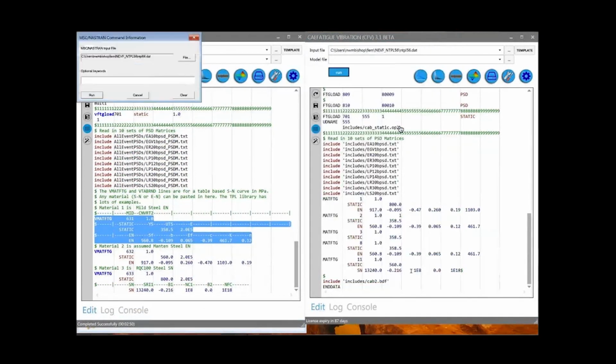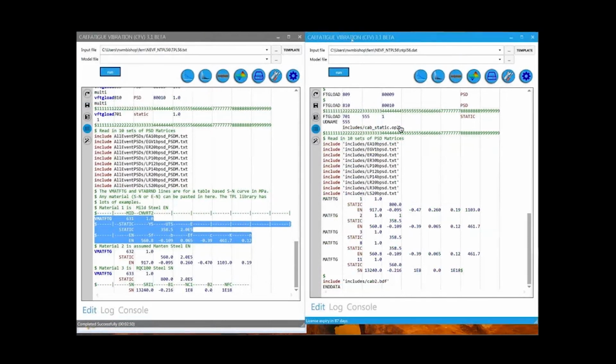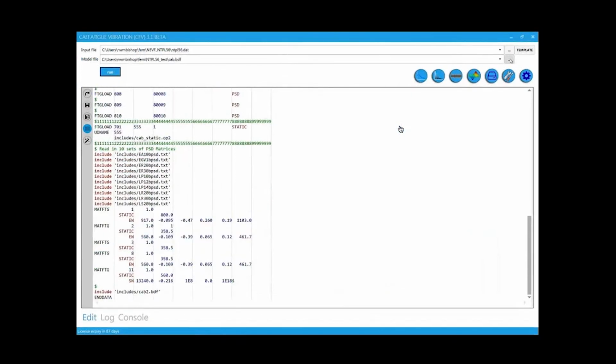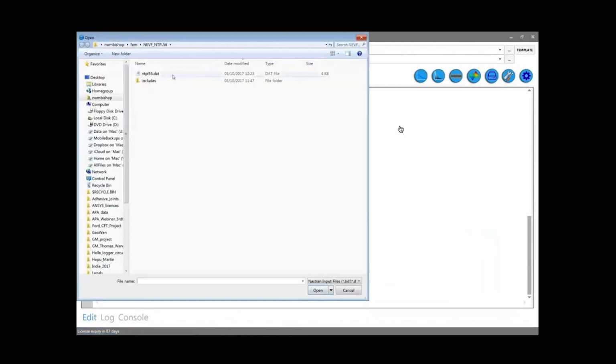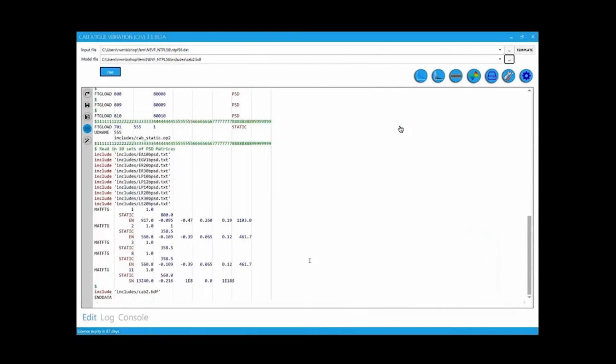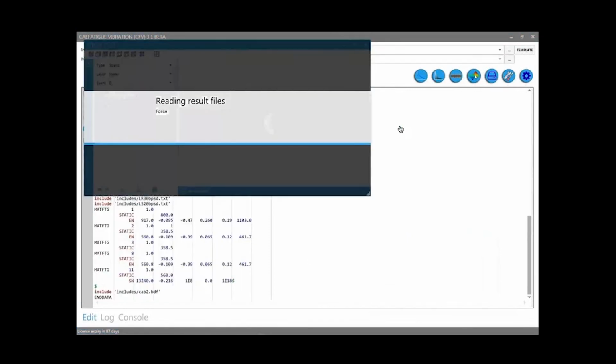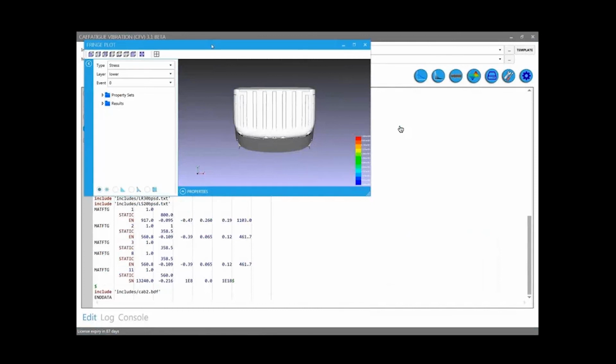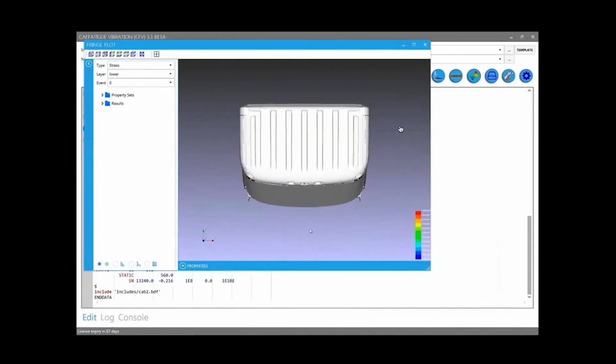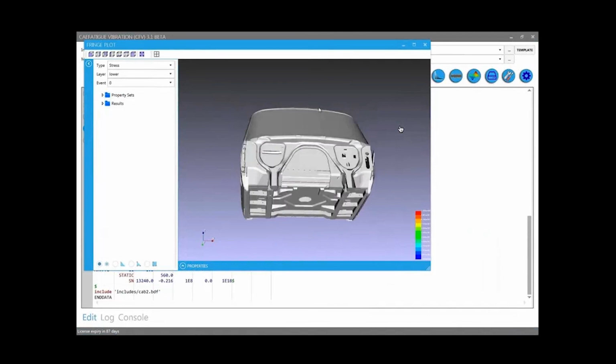Okay, and if I run that, I've already run it. It takes about 5 minutes. I then get a set of results, and those results can be read back into the wizard or the GUI. So I need to load the model cap2.pdf, and then I can graphically plot the Nastran embedded vibration fatigue results in the CA fatigue GUI app. And so that's what I'm doing here.